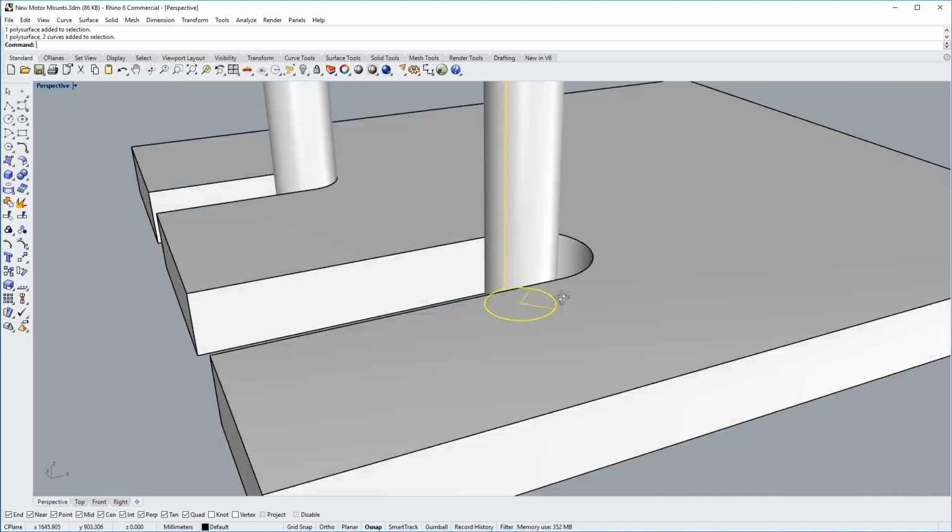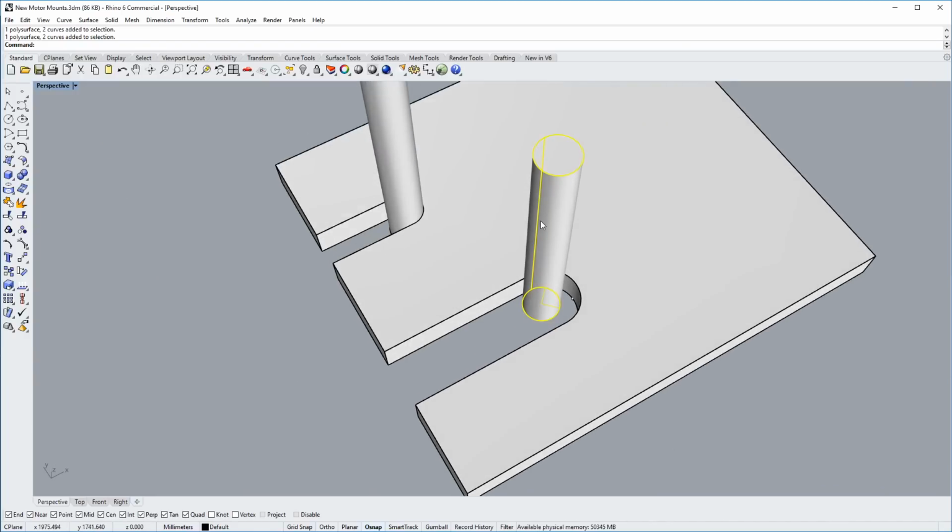Now there's many toolpaths, but basically you have that bit and you sort of cut a larger channel with it by going back and forth with the bit like that. And then, you just progressively work your way down that cut. And doing it like this, you could be as little as 25% engagement with that milling bit, which is going to save the life of the bit, make you less likely to break it, and actually make cleaner cuts. So this is definitely an advantageous way to do things, and it's not an option in Carbide Create.